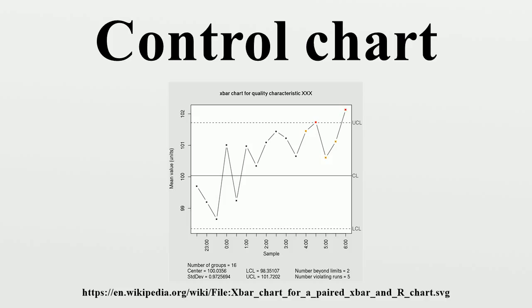The control chart is one of the 7 basic tools of quality control. Typically, control charts are used for time series data, though they can be used for data that have logical comparability. However, the type of chart used to do this requires consideration.